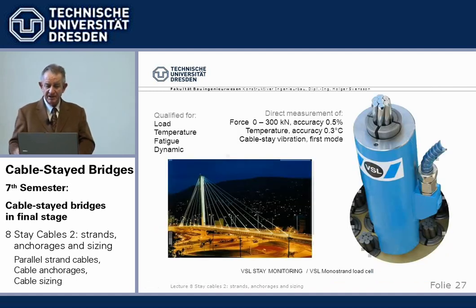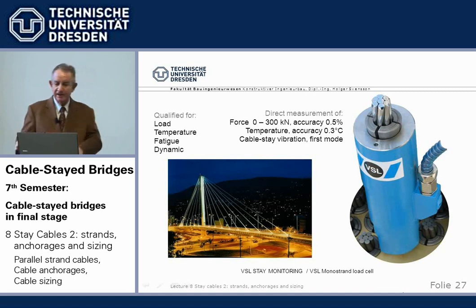Then we can permanently, directly measure the force in the cable by installing a load cell, we call it, which is basically a hydraulic jack, into the cable anchorage.